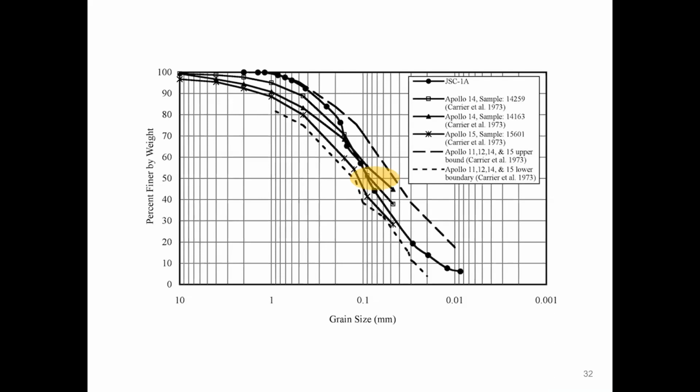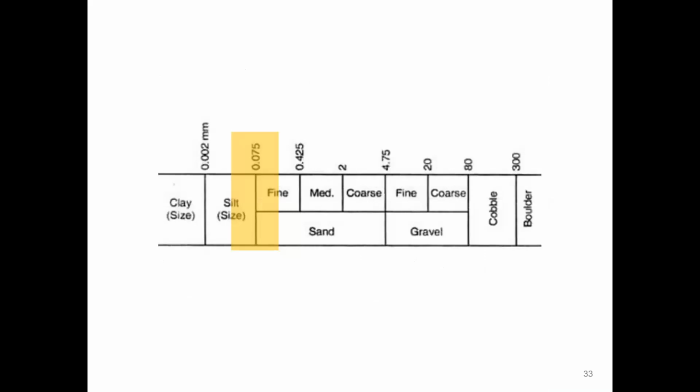I'm going to pause here for a moment to let that number sink in. 100 microns is 1/10 of 1 millimeter. So that's pretty small. Lunar regolith is similar to baking flour or talcum powder as far as particle size is concerned. Analogies have been made to fine-grained slag or terrestrial volcanic ash, or to a dry silt bed in the desert, which means that medium and coarse sands and gravels don't really do a terrific job of simulating lunar regolith particle sizes.